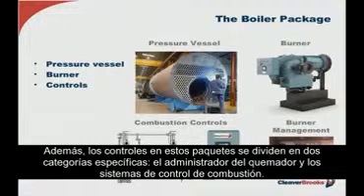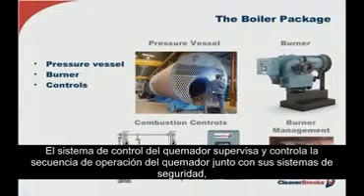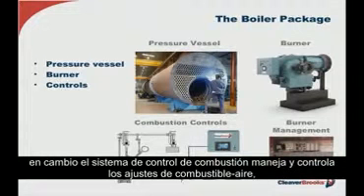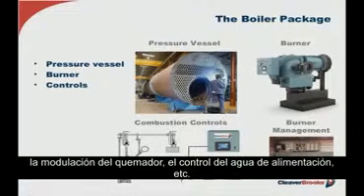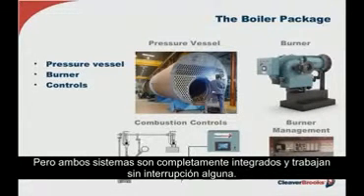And I also wanted to mention the controls on these packages are broken down into 2 very specific categories, which are the burner management and the combustion control systems. Very simply, the burner management control system is supervising and controlling the burner sequence of operation along with its safeties, while the combustion control system is managing and controlling the fuel air settings, the burner modulation, feed water control, draft control if applied, and so on. But both of these systems are fully integrated and work seamlessly together.